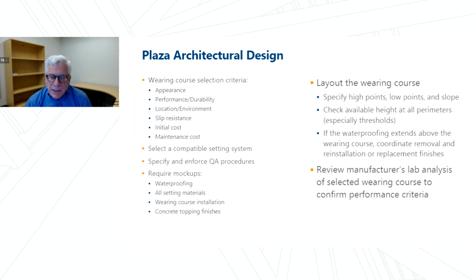And what we always recommend is mock-ups. Mock-ups really give you a lot of information on appearance, the ability to install these, and also it verifies the level of craftsmanship of the people actually doing the work. The layout of the wearing course is important with regards to the waterproofing below and how that goes together.